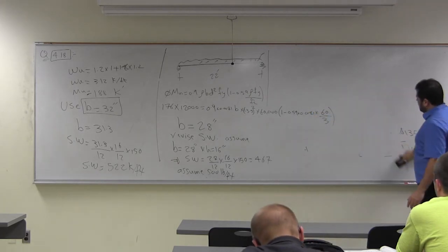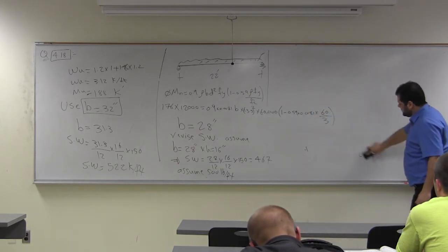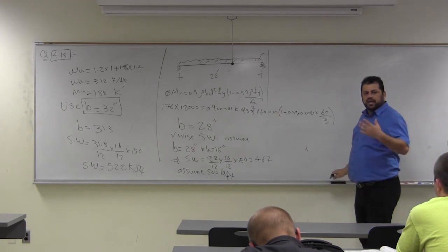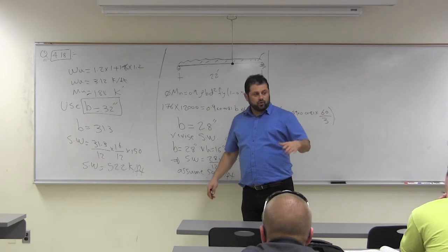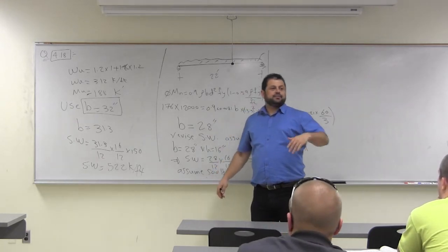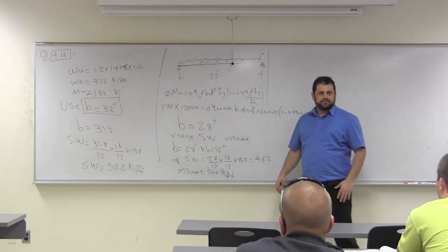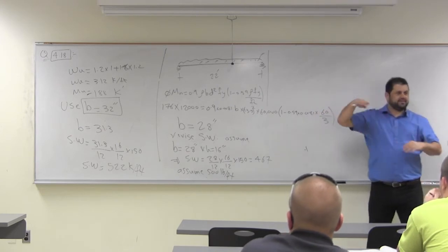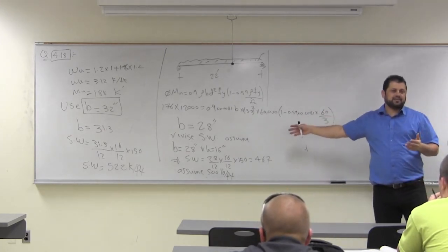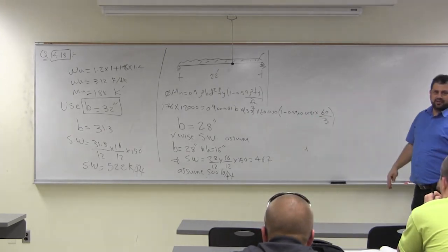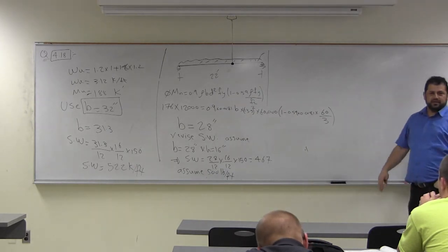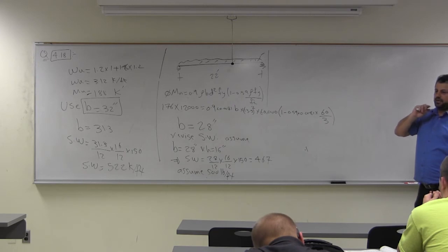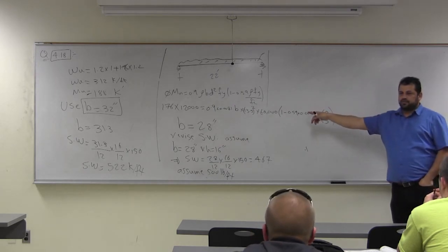That's not a normal beam, guys. Usually when we design, we like to have H between 1.5 to 2B. But here you are limited by the architect to 16 inch. That's why you ended with something like that. But usually you have B 10, 12, that much, and you have D higher, or H higher. How much do you get?